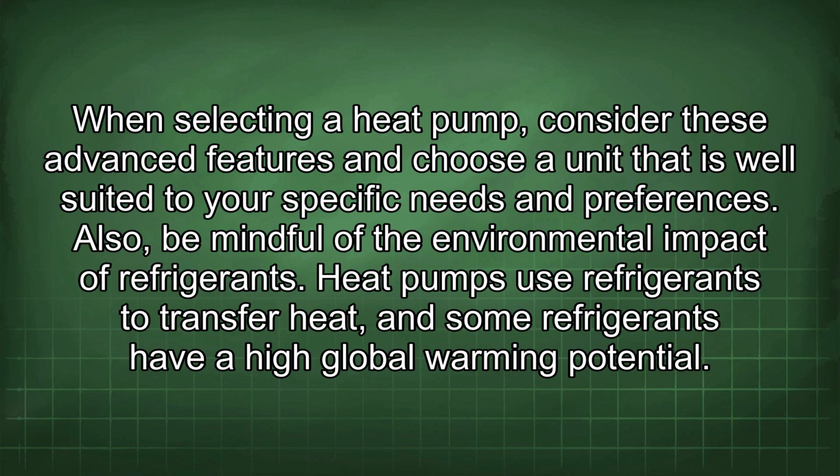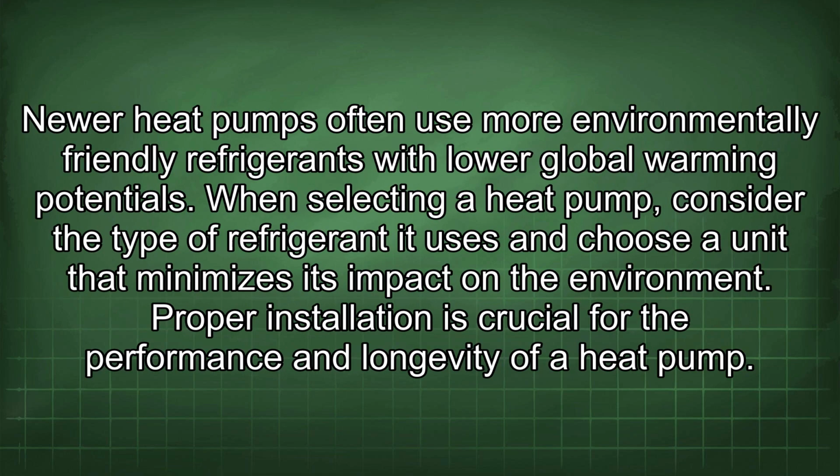Heat pumps use refrigerants to transfer heat, and some refrigerants have a high global warming potential. Newer heat pumps often use more environmentally friendly refrigerants with lower global warming potentials. When selecting a heat pump, consider the type of refrigerant it uses and choose a unit that minimizes its impact on the environment. Proper installation is crucial for the performance and longevity of a heat pump.